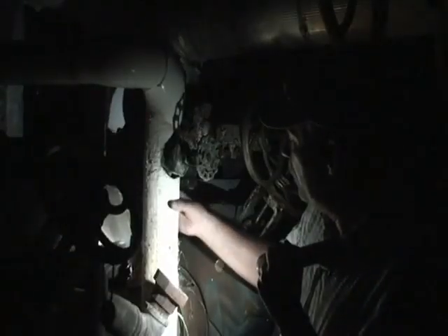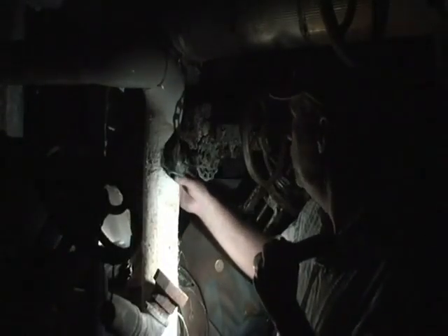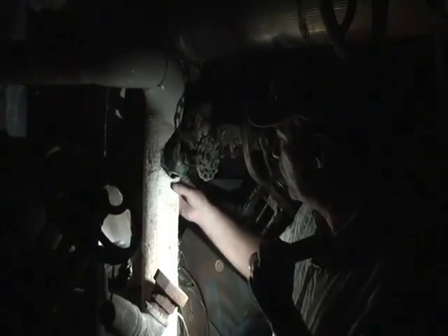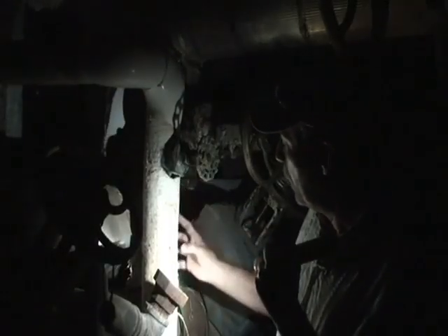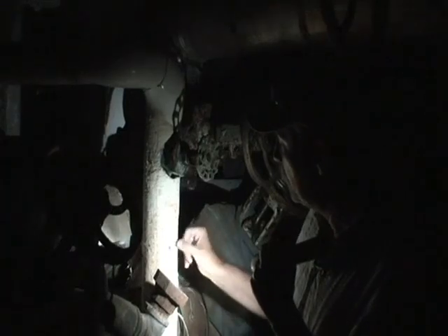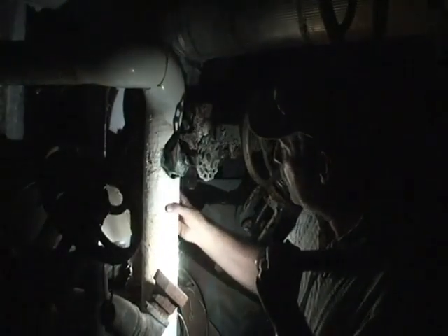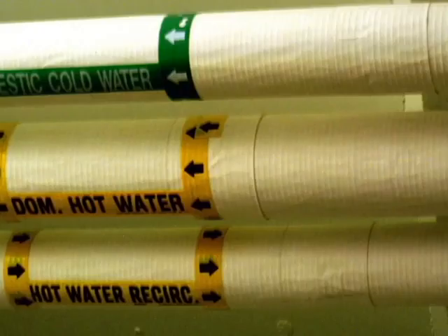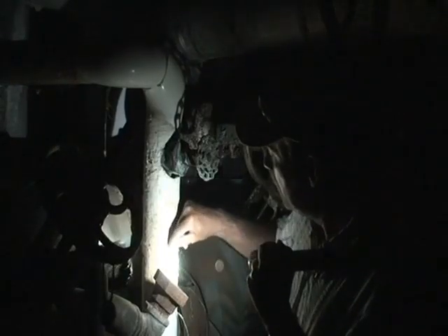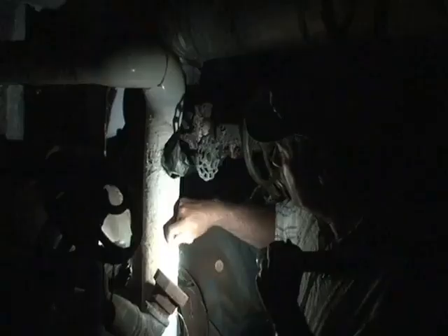Another way of identifying a pipe insulation or any kind of insulation as a fiberglass material, if it's not readily visible, if you can't see the pink or the yellow stuff underneath: if you look at the outside wrap here, you can see these thin string striations that run the length of the insulation. They're in between the outside paper layer and the fiberglass material underneath. It just kind of gives extra support to the outside layer.